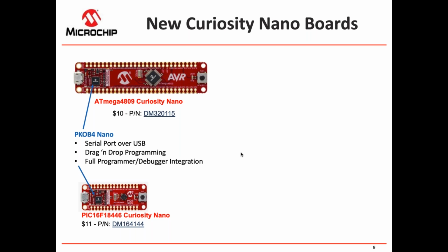And if you are an AVR freak, then that chip does the function of an ICE. So you have full programming and debugging from inside Studio if you are in the AVR, or MPLAB if you're on the PIC. And that is a lot of functionality in just that little tiny chip. So this is cool, and it's in the right form factor. We like it. It's very low cost and it's very effective.